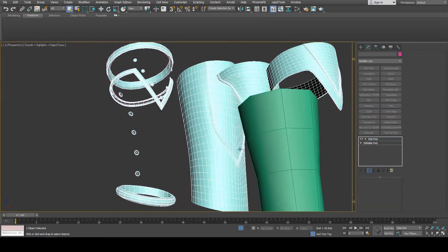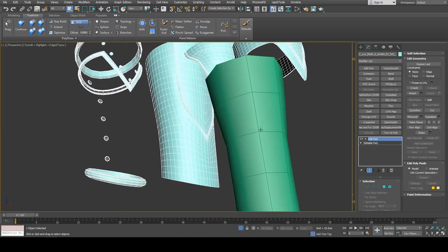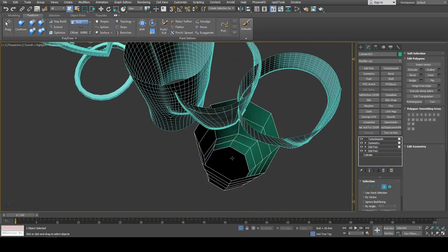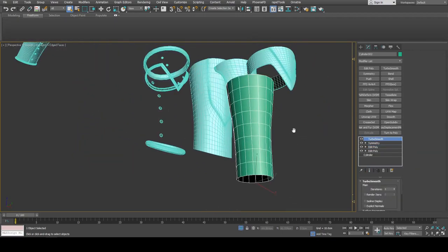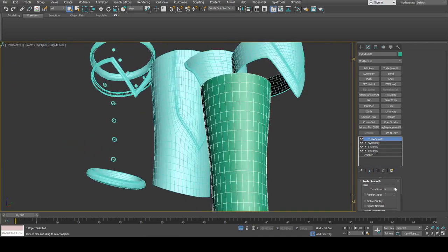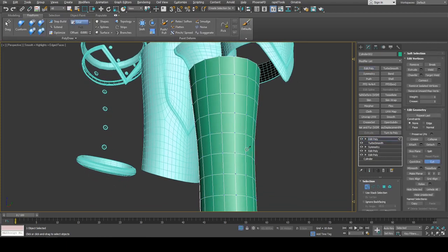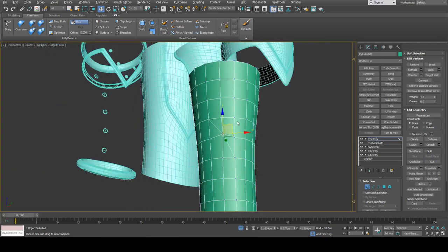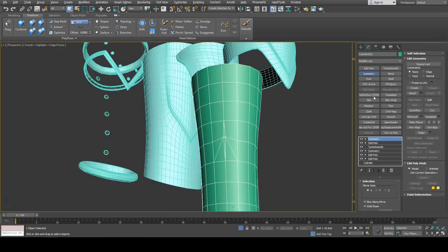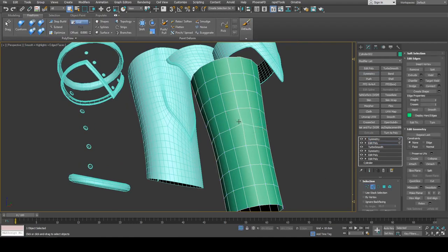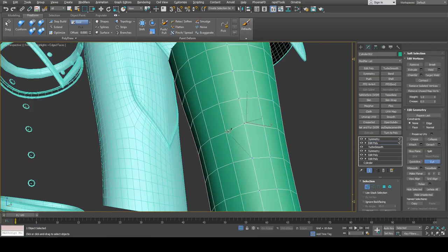Alright, so in order to get this kind of built-in object that's not a separate mesh, I can apply Turbo Smooth. I'm going to delete the ends first. Alright. Maybe go with one or two iterations here, and then what you can do is use the cut tool to kind of cut this shape. Let me just kind of move around a little bit. Actually, I have kind of cut the wrong area here, so I'm just going to remove this. All right, let's cut right here.